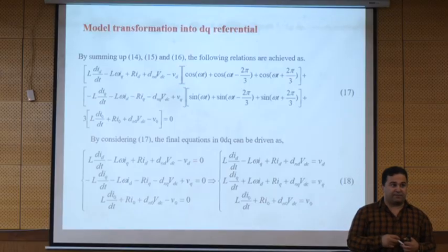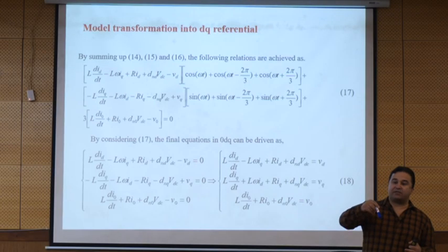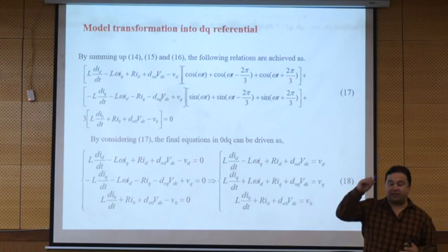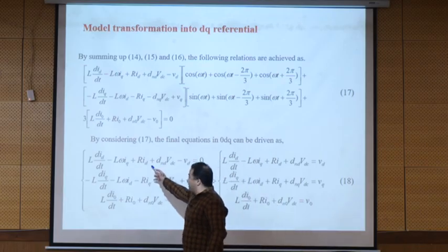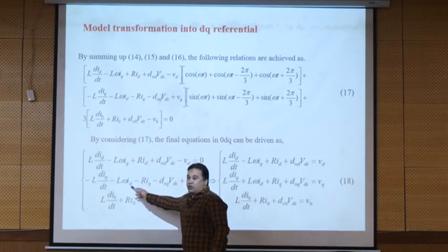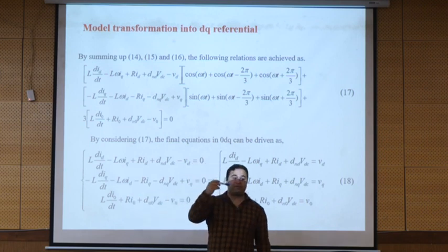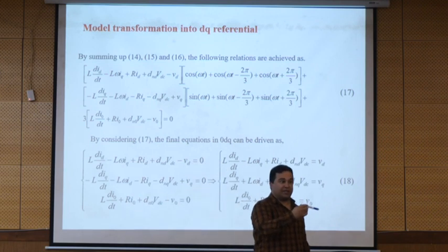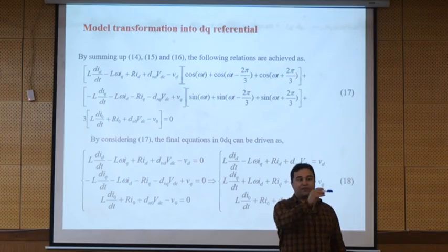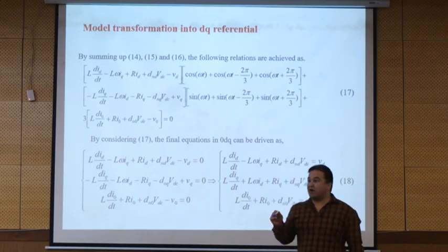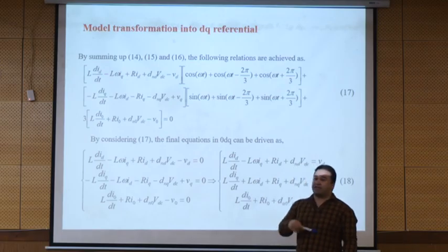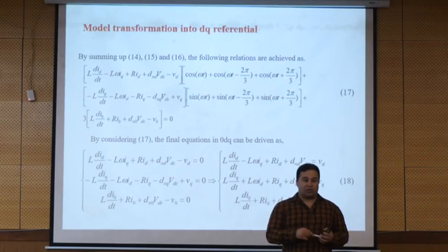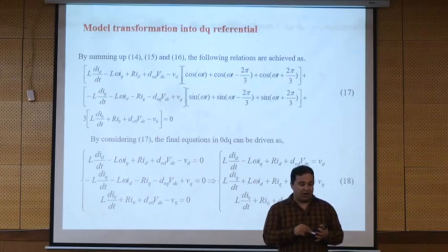When we have this power increment, in fact we changed the Id, but this Id appears here in the Q axis. But the Q axis also refers to the reactive power. So you see that reactive power is 0, but when you have this, we have a spike here. So for this case, we should find a solution to remove this part, and we call it decoupling.